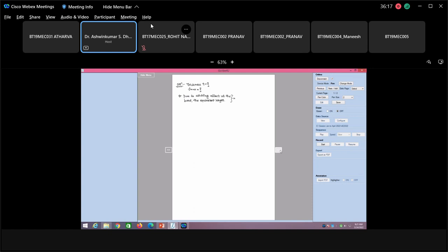So that is why you need to subtract the width of the band from the total length of the leaves. So it is 150 minus 10, that is equal to 140 centimeters, and use this particular length for all the calculations. So this is basically what I wanted you to understand, because what is going to happen, suppose